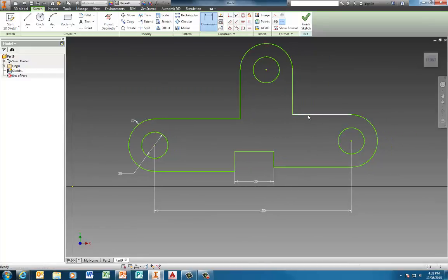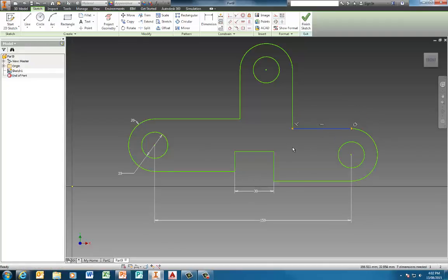One of the other things that we'll see here, that even though these lines are the same distance apart because the radius of that arc is the same as this one here, so the spacing top to bottom is the same both sides, we've got this variation here. Now this can be very easily overcome using the collinear constraint.